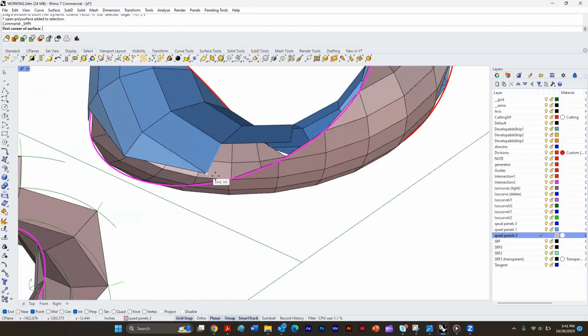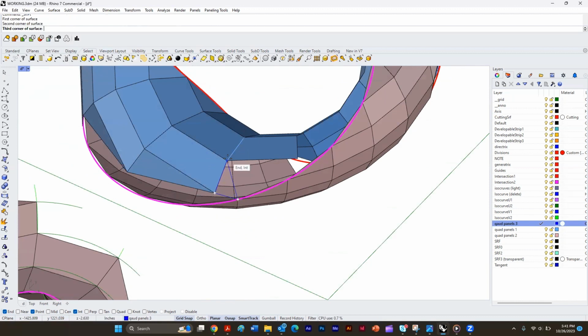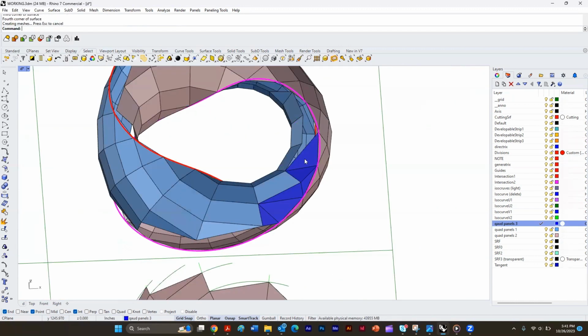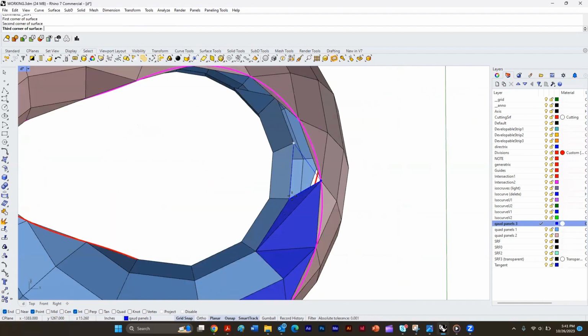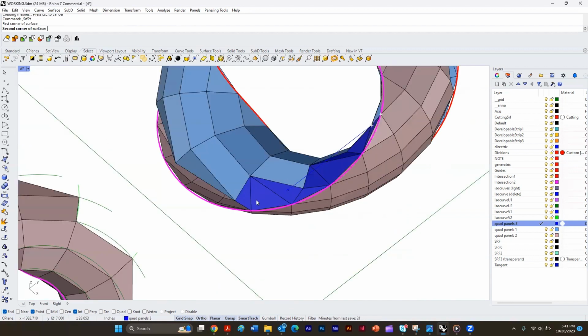And so then I am going to fill in the rest actually just with triangles. So we often try to avoid having triangles, and that's what we're going to try to do mostly in this class. And there's a couple of reasons for that. One is when you're building things, you're mostly building things out of planar sheets of rectangular material, and so you waste a lot of material if you're cutting things into triangles. Also, triangles are visually busy, very distracting. Also, there's a lot more joints, a lot more structural nodes, a lot more possibility for leakage every time you have to have a joint.